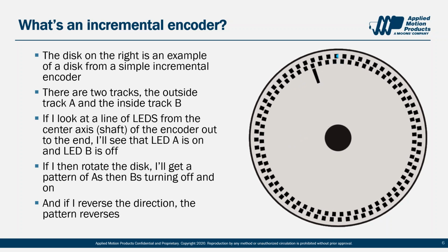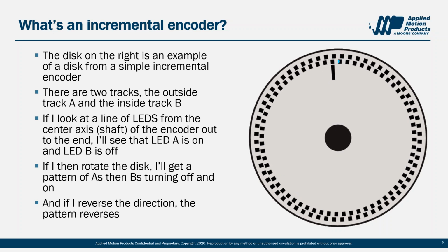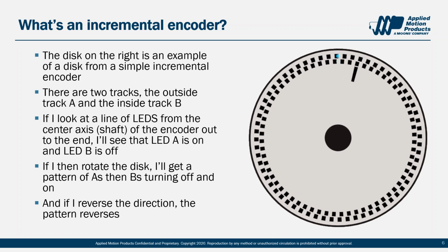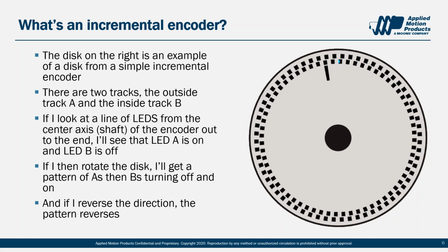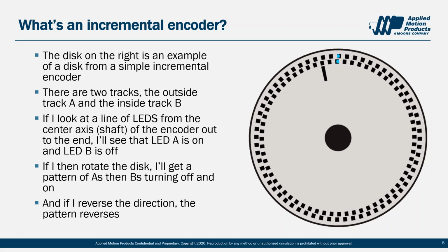However, at any given instant, the encoder really only has 4 states. So taken as a point in time, the incremental encoder is useless as a positioning device. It relies solely on the drive to track the number of pulses and therefore track the position.